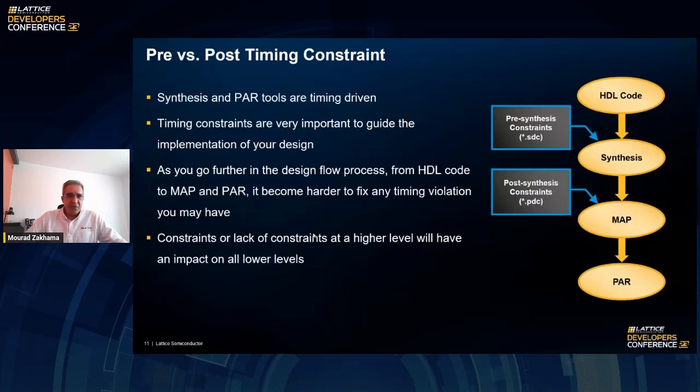So, pre-synthesis versus post-synthesis constraints. You have the diagram on the right where you have the HDL code. The HDL code will go through synthesis, map, place and route, and after that you generate the bitstream. Keep in mind that the synthesis tool, map, place and route are all timing driven. The sooner, or the higher in the flow, you fix problems, the less chance you're going to have to fix them later on in the design process.